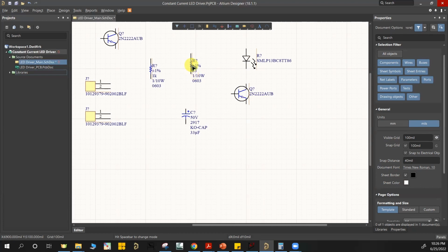Again, this one is the one that I had readily available in Altium, but since it's a generic footprint, a 0603 SMD surface mount device footprint, we could basically just swap out that part number for 20 ohm or any other resistance values if you want to. So for now, I'm just going to select this 33 ohm. We're going to place it right here at the emitter of this transistor.